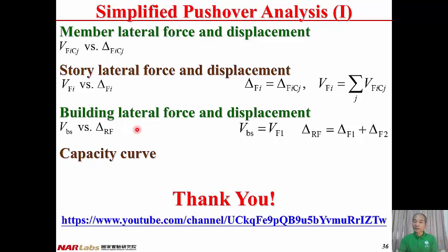And from the story level, we can move to the last stage. That's the building level. And in building level, we would like to find out the force relationship of a structure. That is base shear V against delta roof. And base shear V equal to VF1 if the first floor is the base. And delta roof equal to delta F1 plus delta F2. And from this relationship, we get the capacity curve of the building.